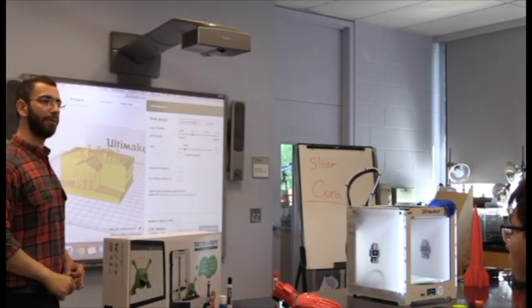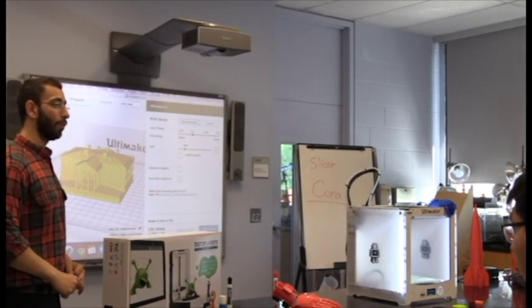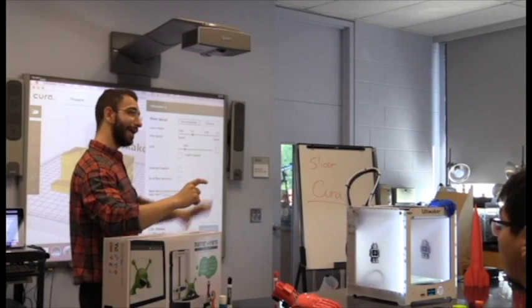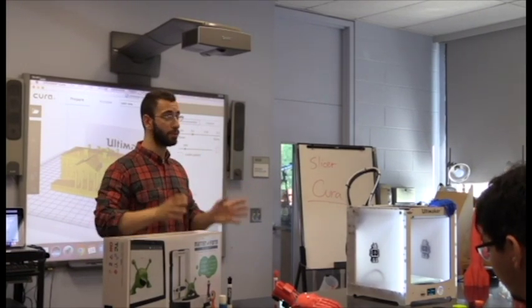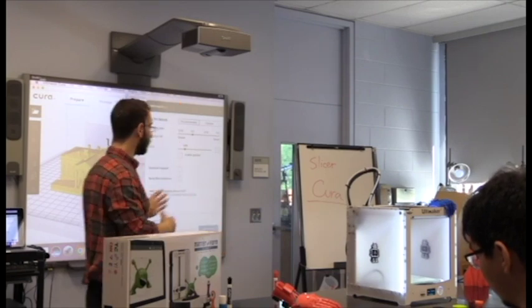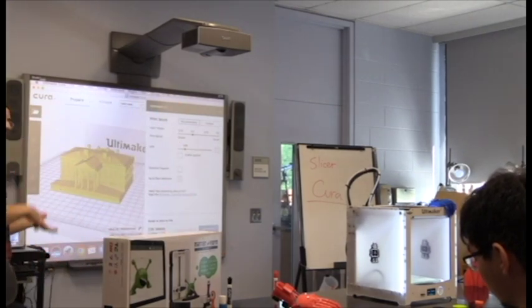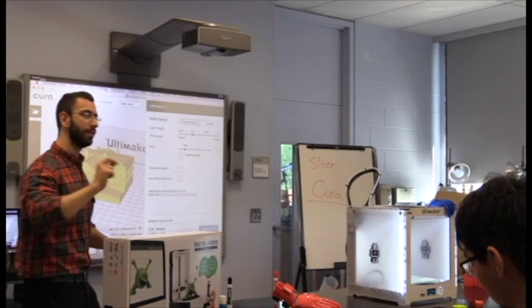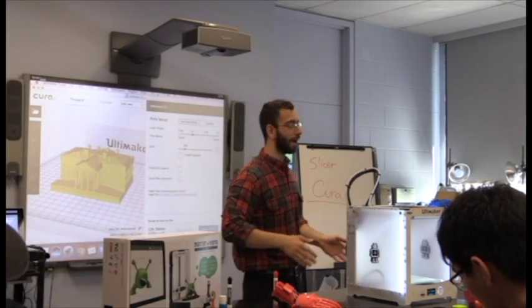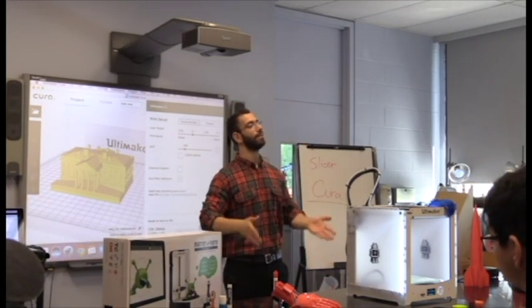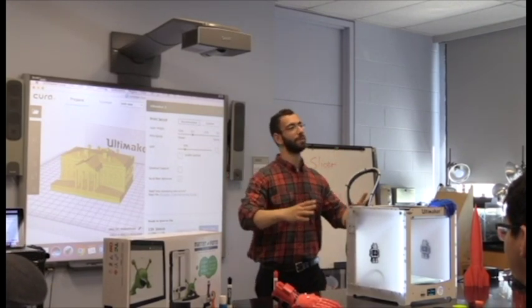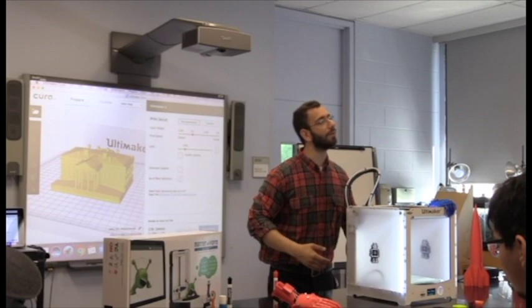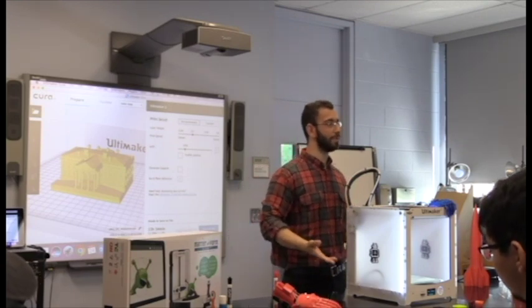You need an STL file to work with a slicer. Where do you produce the STL file from? From CAD software. You literally export as an STL file. That's what you need to 3D print. A slicer can only read STL files. Also, they read object files, .obj. The most common one, you're always going to hear people saying STL. That's like the international file extension type for 3D printing. People are going to say, well, you have an STL? That's the only thing you need to be able to 3D print.